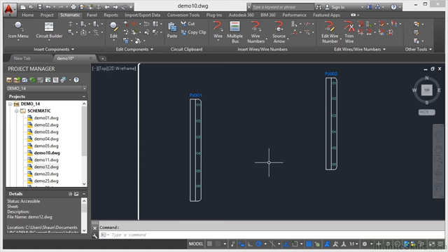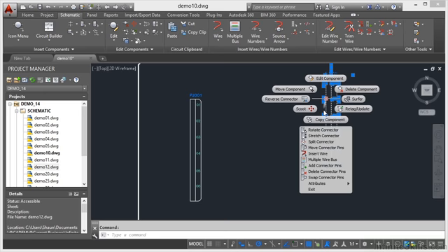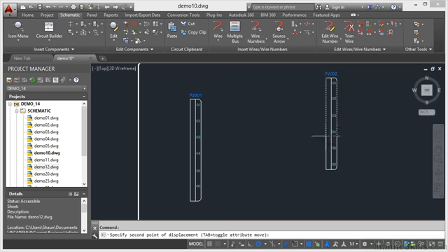Let's have a look at PJ002 here and stretch that one as well. So what we'll do is we'll select the component this time, right click, and you'll notice that we've got the ability to stretch the connector. And it's the same process, but this time, can you notice it automatically starts from the top? So I can stretch upwards, or as I come down, it stops. This time, it depends on which end of the connector you actually select the component.